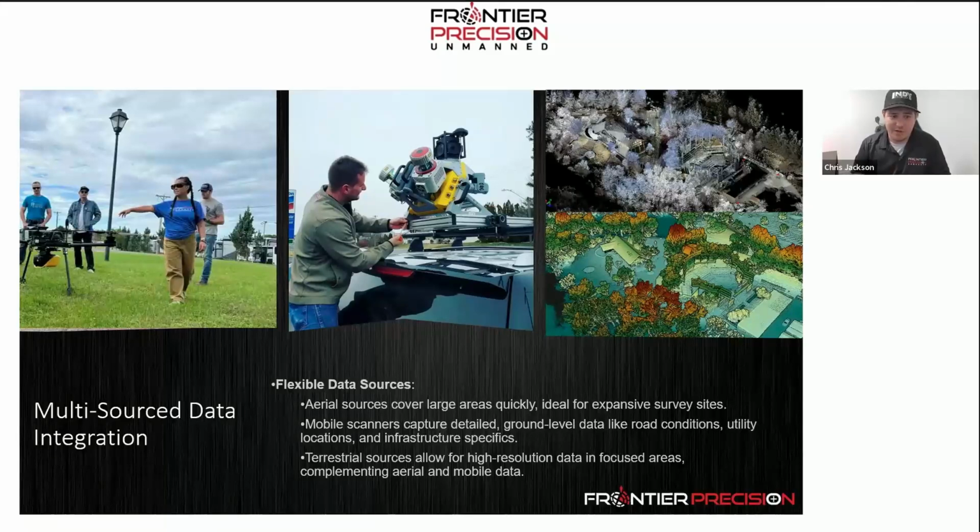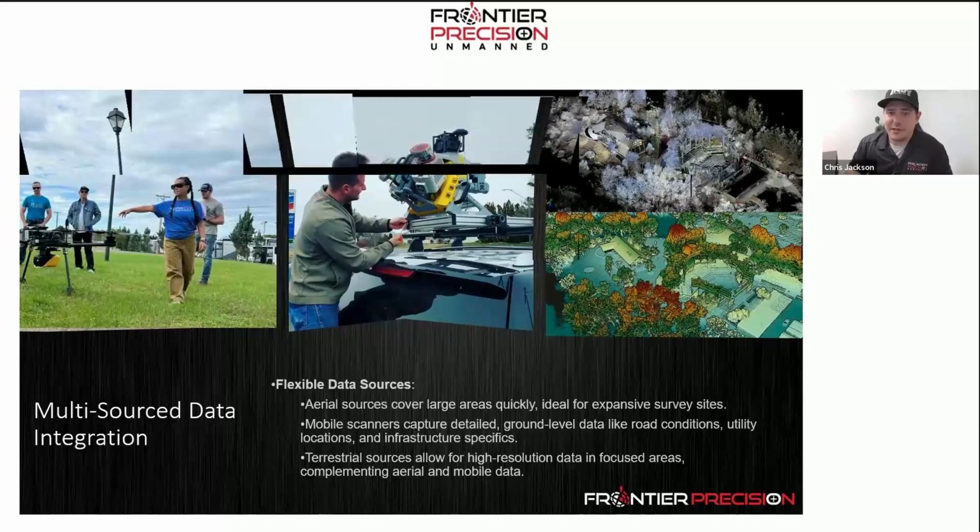Whereas now, with the help of AI, some of our automated workflows, and the power of Trimble Business Center, it's much easier to go out and fly a site with aerial LiDAR and photogrammetry, and then do a mobile scan, as well as a terrestrial scanner, and then walk around with your rover shooting GCPs. We can add all of that data from all those different pieces of equipment into a single project to make the richest products possible. So definitely a huge step for us there.